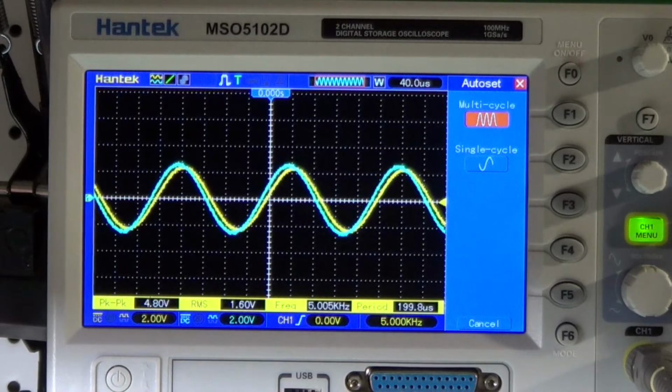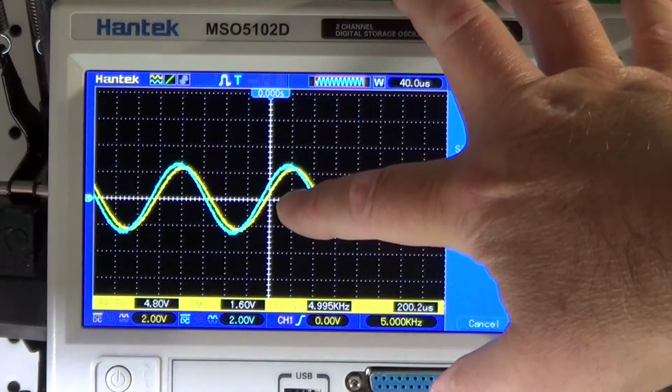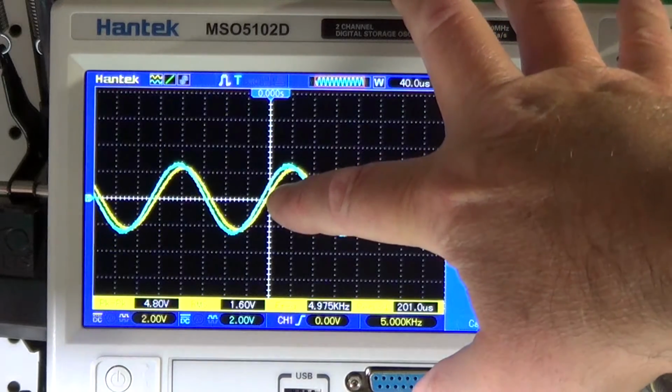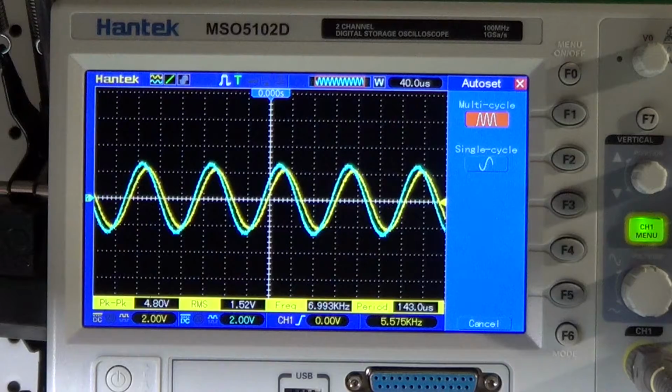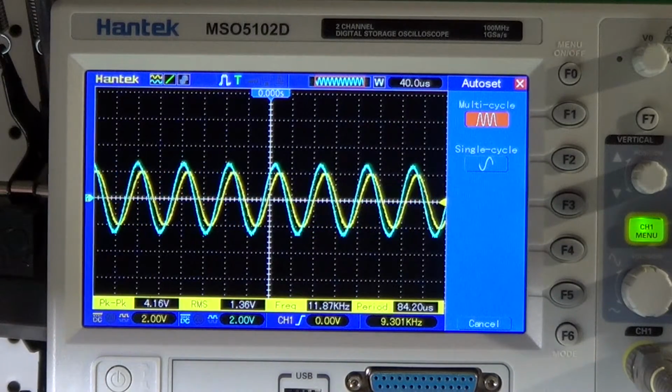You can see basically that the yellow comes right after the blue, which means that once the signal reaches a certain level on the input, the same level is reached on the output only after a while. So we say that the signal on the output is getting behind. And if we do this any further, if we keep increasing the frequency, look what's happening.